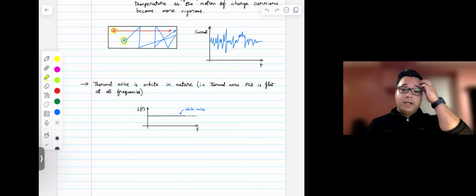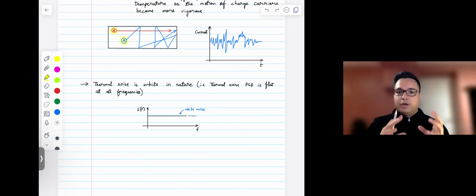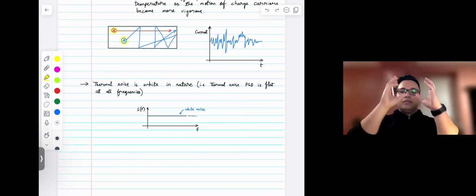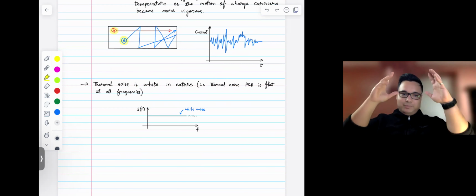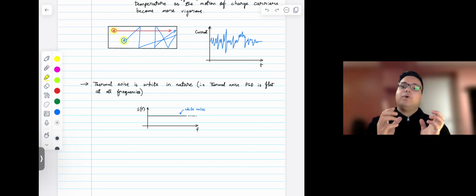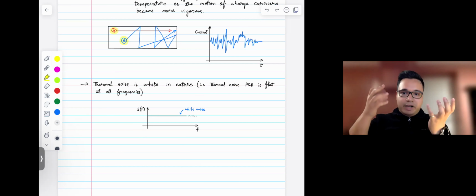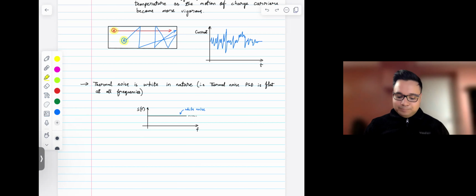This is common in electronics for scientific instruments, or you might have seen pictures of a quantum computer where they have all of the quantum chip inside a dilution refrigerator, which is basically trying to keep all of the electronics as cool as possible. One of the reasons is that you just want to reduce the thermal noise in your resistors, in any conductors really, as much as possible by cooling down the temperature.